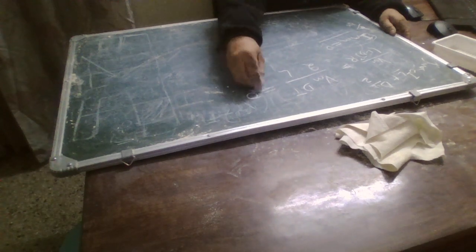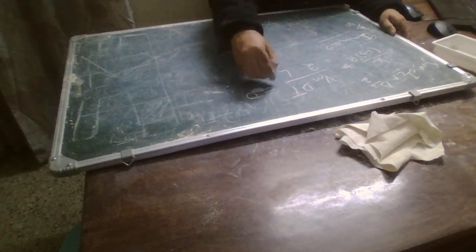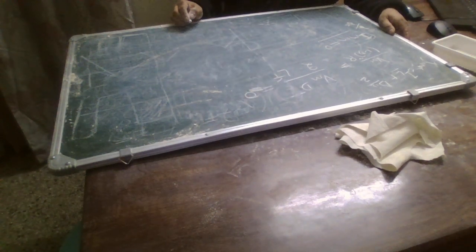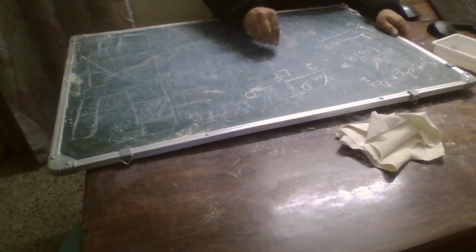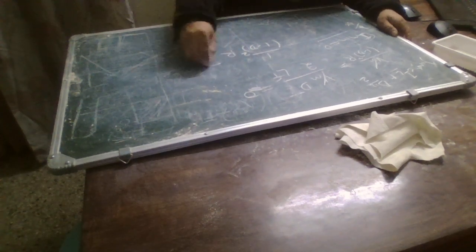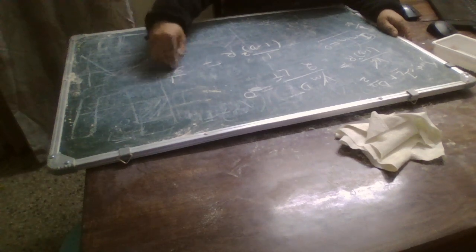Solving it, we can very easily say this is going to be equal to this thing, and we know T is 1 by F, so we can put F here. V input and V input will get cancelled. We have 1 upon 1 minus D the whole square R equal to 1 by twice LF.